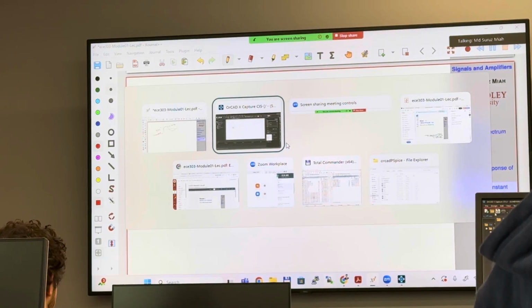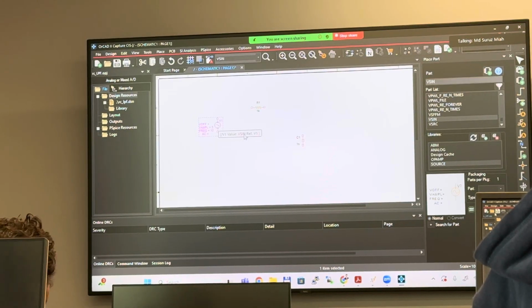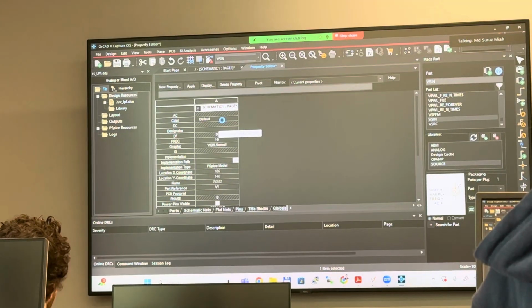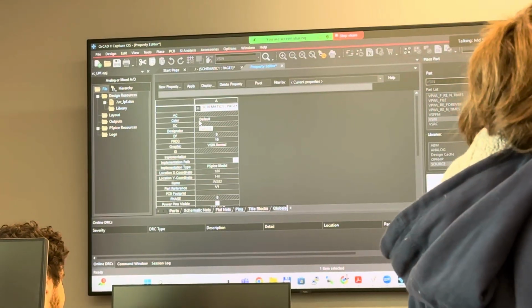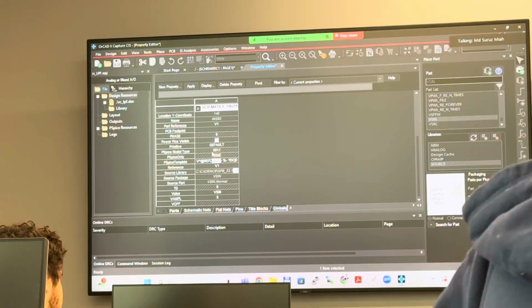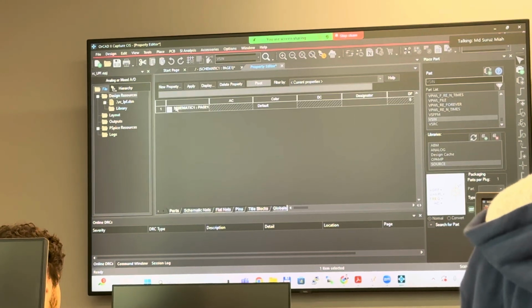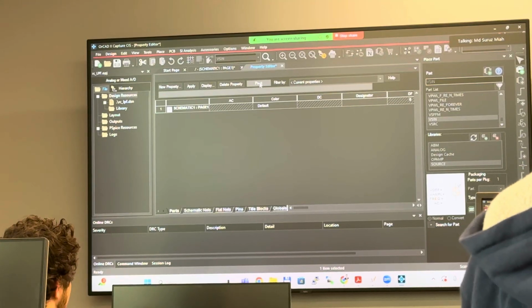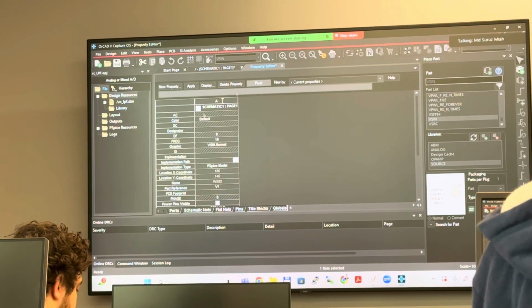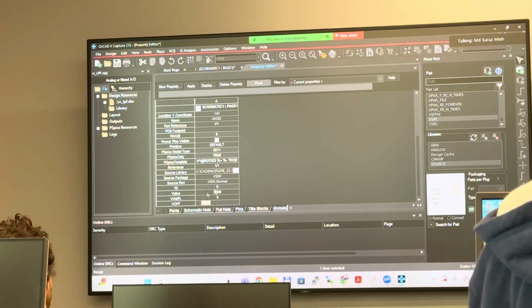So what we do, we go right here and then double click to see the property editor. Initially, if you don't see all the parameters in a parameter table like this, you might see it like this. In that case, you don't see all the parameters. So what I would suggest is that you click pivot, then you see all the parameters as such.